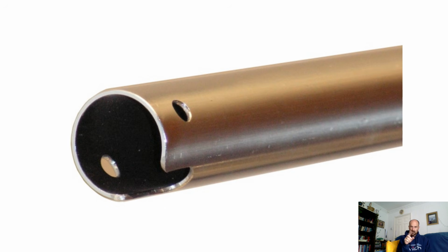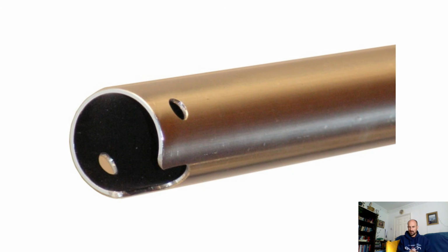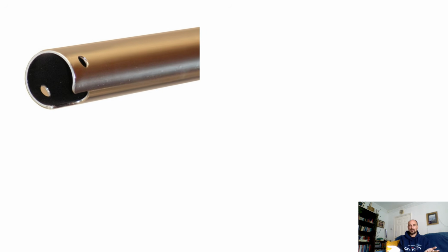But yeah, as I say, on the uprights we got really good data, and on the wires we didn't get any data. But let's go into the stuff on the control frame on the uprights a bit more now. We're comparing 3 different profiles for the uprights. We're using a round cylinder as a baseline. We don't actually make gliders that have round uprights anymore. Our standard is the rubber backs now, but it's a good baseline to use, and also because the round base bar we do use with the rubber backed uprights, so we need to know the drag for that as well.